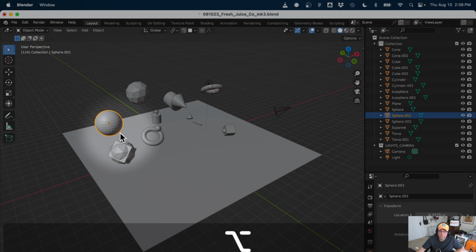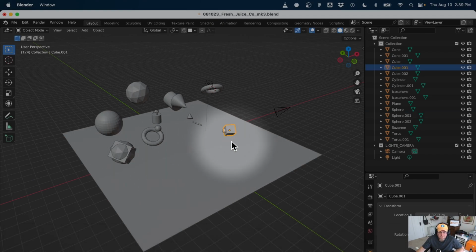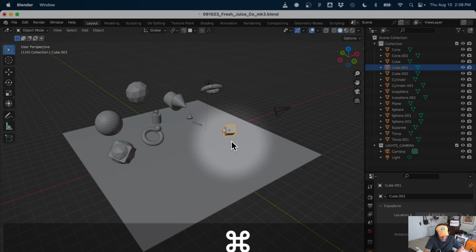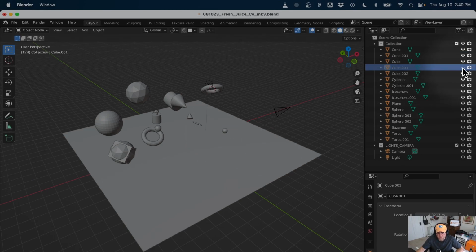This is similar to removing the transforms on an object. Remember, whenever we press Alt or Option on a Mac and then tap R, we can get rid of rotations. Sorry, I'm just going to Command C that. We press and hold Alt or Option and tap G, and that'll move it back to its starting point. If we tap S while holding Alt or Option, that'll change it back to its original scale. So I'm just going to set that back so that you can see that. Again, whenever you press Alt or Option, that undoes something. That's just a standard thing to remember.